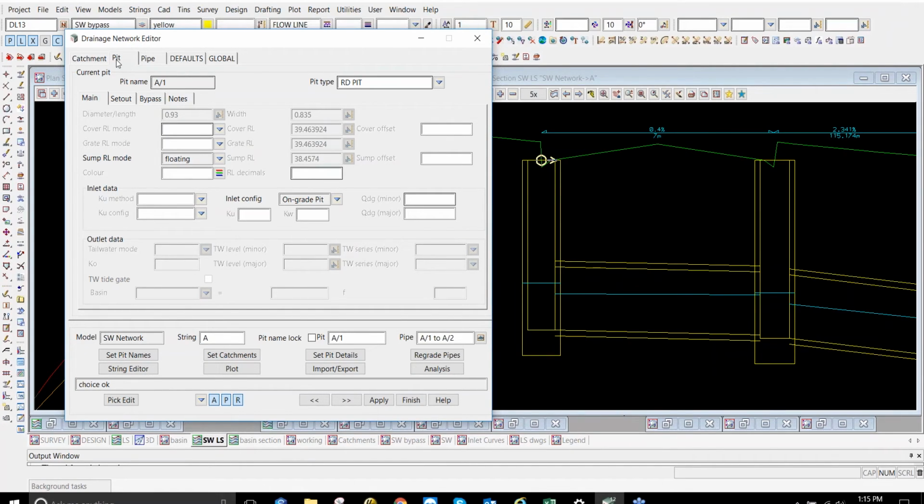So our system now has been graded. We've got the minimum grading. We've done the pipe cover. We also make sure that we don't clash with the other services. 12D is a full service package for modeling all your different conduits, everything from lamp posts, foundations, to your electricity, your Telstra, your telecommunications, all those sorts of things. So we check for service clashes at this point to make sure that at least we have a plausible network before we send it across.